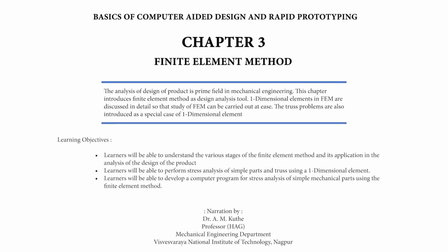Para 3.1.5 Finding the unknown. The global matrix equation is solved using the Gauss elimination approach and applying boundary conditions to get the value of the displacement at global nodes. Using the value of displacement at the nodal points, derivatives of displacement, that is strain or stress over the element domain, can be found out.